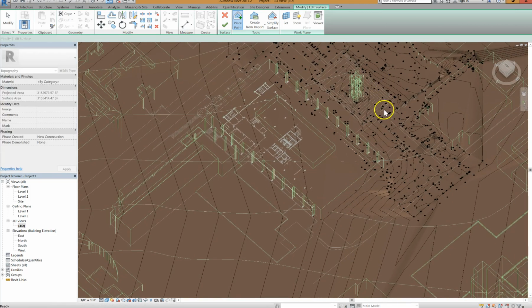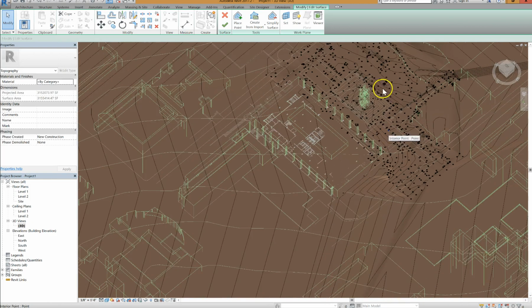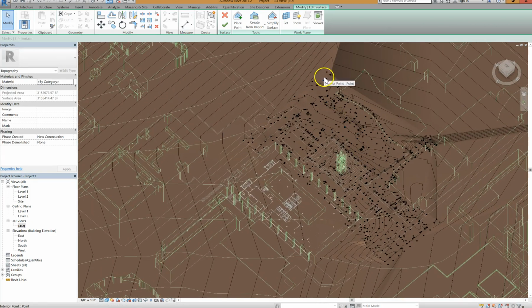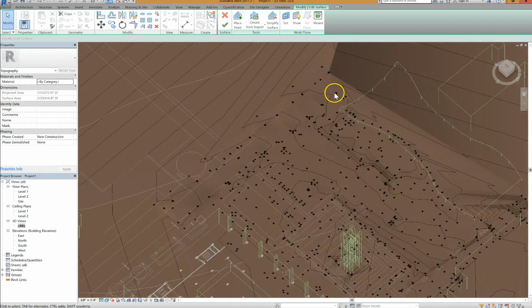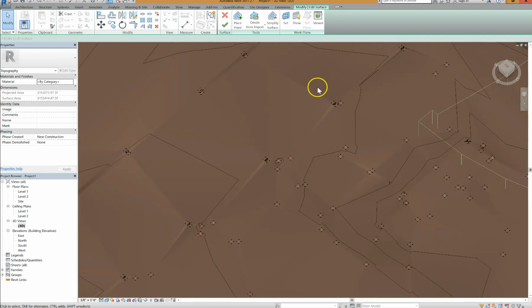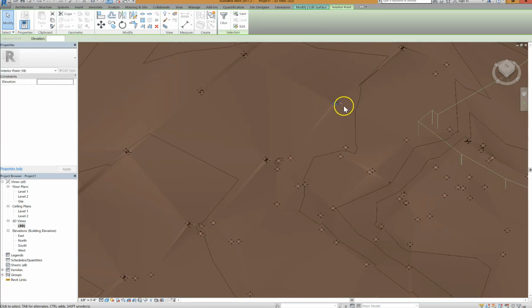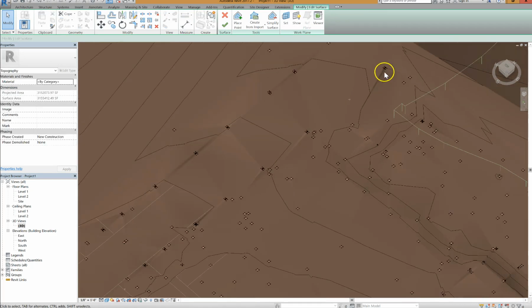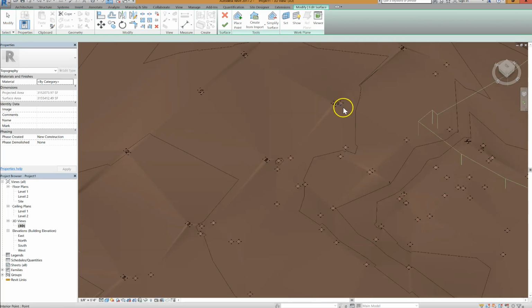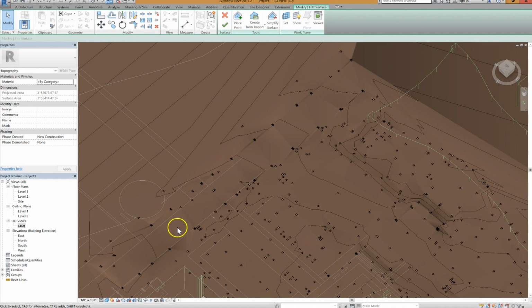What you're also going to find is as you edit the topography, one thing you're going to want to do the most is delete all of these points. If you don't need all these points, you dump points. And I'm just going to remove some here, and you can see it kind of levels out the topography as much as it can through there. But no, I'll hit undo and put those back. And you can see what it's doing. We have good accurate topography that's even showing the road passing through here by the way the topography lines that Revit creates are going through.